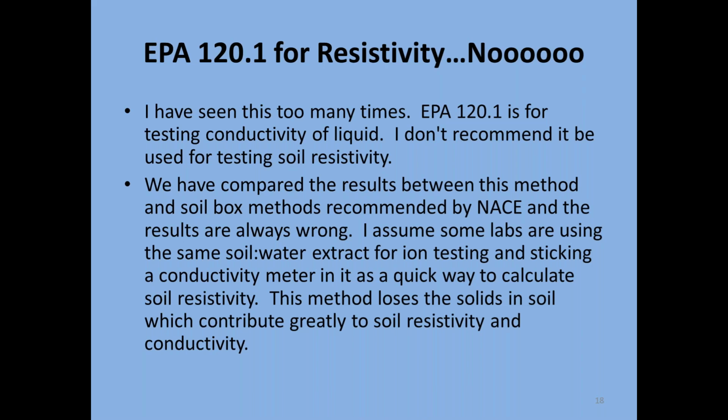And then many environmental laboratories take the liquid extract, filter it, and then start running it through their machines, and they test the conductivity of that liquid. Okay, and the inverse of conductivity is resistivity. So basically what they do is just take the inverse of that conductivity read and determine resistivity, and that's what they report. But with all the filtering and so forth that they've done, they've removed many of the contributing factors of that soil. So that's not a good way to measure soil resistivity.